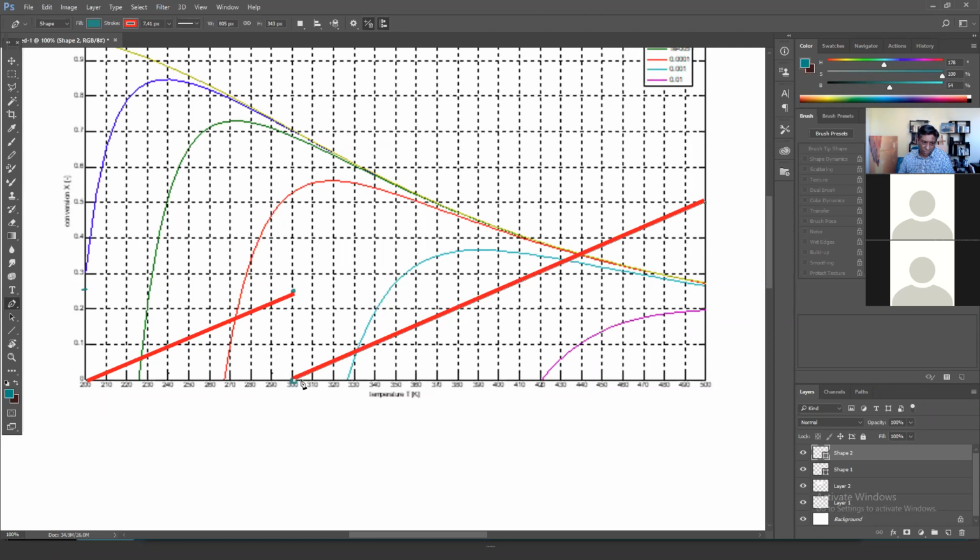So we start at 300 Kelvin, and as we increase the volume of that CSTR, we will be moving through points, moving up like so. And then in this region, we get very low rates. If you consider a very small change in conversion along this line, it might be hundreds of cubic meters, right?